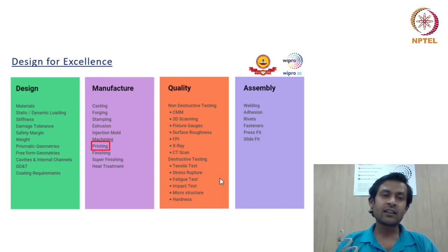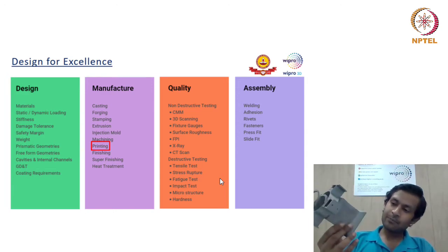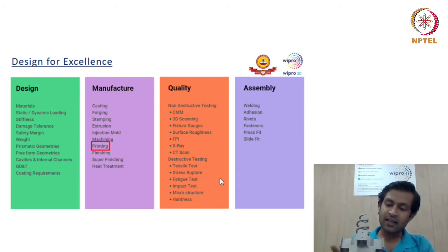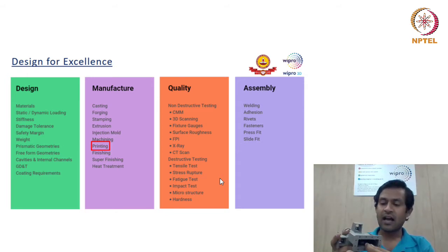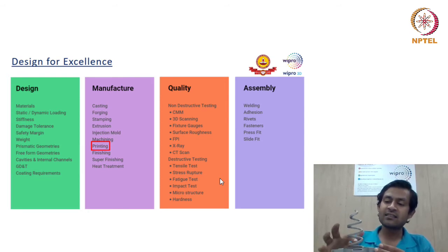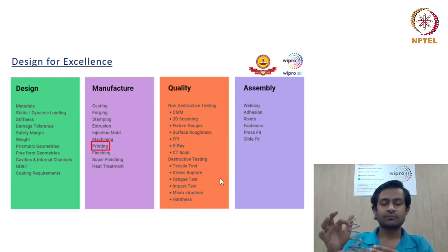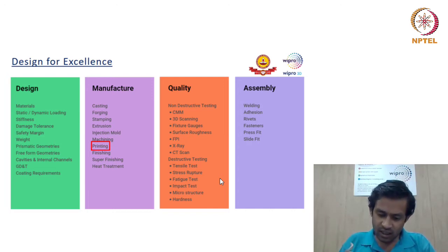This is an RF antenna of a satellite communication module. Basically, what is happening in this RF antenna is that there is an RF signal which is fed here. There is an RF signal which is fed here, and these are mounting points which are used for mounting the component. And then the signal is transmitted using this helical structure. Now in this component, the helical structural profile accuracy is very important.